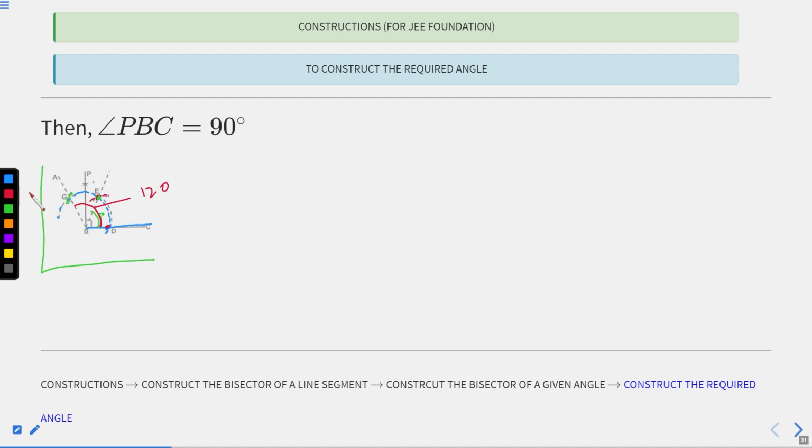Okay, and now taking this E as a center and making more than half of the length and making that as our new arc radius, marking another arc like here, and now shifting to center at G with the same radius as we took in the previous step to mark this orange arc, and we mark here another purple arc, and this intersection P we will get, and this will be the angle bisector which makes the 90 degree angle, which is angle PBC.